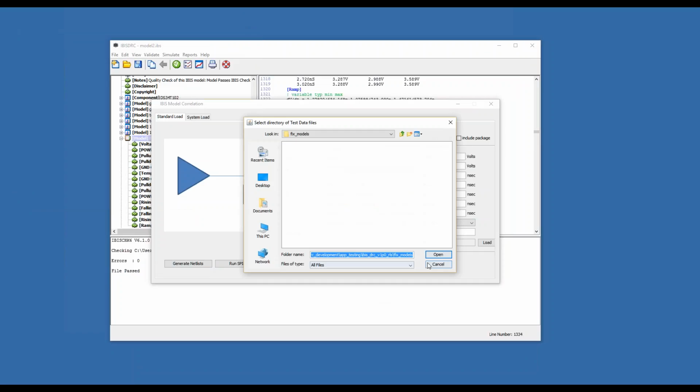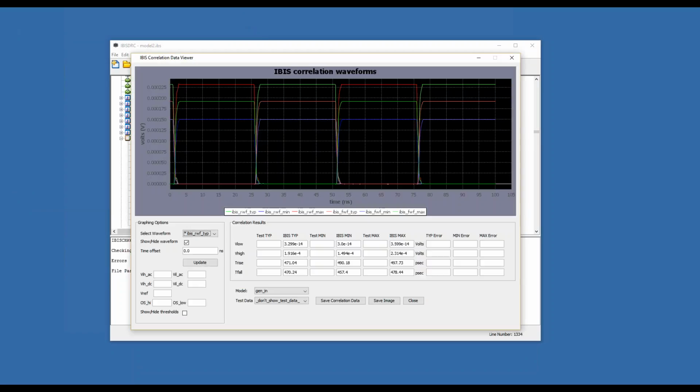And open. So if you look here, what we're showing is your 3 corners, typ, min, max, just running a simple pulse input into the standard load, which is a capacitor load. So it seems like it's switching okay until you go up here and you look at this output voltage, 0.001 volt. So essentially, what's happened is this output is not switching properly.